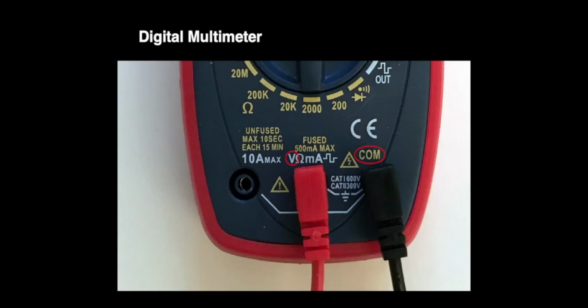Here we have the voltage and COM channel, and this is what we are going to be using for this class because we're only working with DC current. This is the negative and the positive. You touch the black to the negative, or the minus, on a battery, and the red would be the positive, essentially.